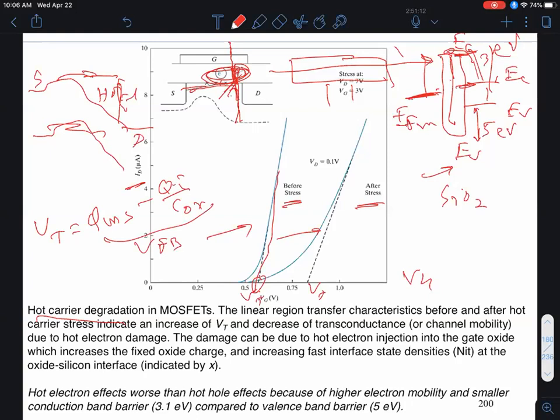Now Qi was the charges in the dielectric, but the weighted sum, right? Charges close to this dielectric count more, charges close to that dielectric induce image charges in the metal gate that don't cause band bending in the semiconductor, right? So you have to do the integral of charge distribution weighted by the distance of the charge x from this interface. So that is 0, that is x, dx, integrated between 0 to the thickness of the dielectric d. Remember that integral?